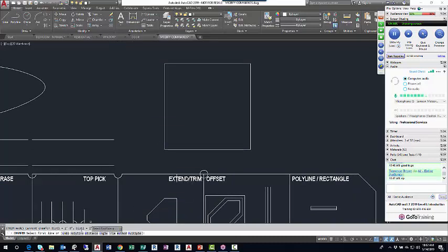Now the distance 1 and distance 2 are already set to 2 feet, but I'll click distance, pretending that choosing the distance is 0. Distance 1, I'll type 2 feet and hit enter. Distance 2, I'll just type 2 feet and hit enter again. And then I can left click the bottom horizontal, left click the right vertical, and that's what creates that sort of beveled corner.